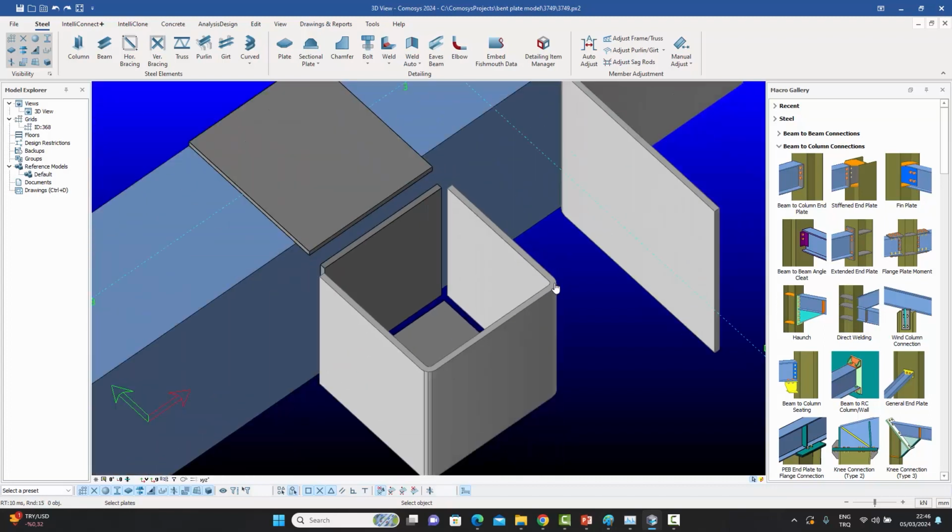it's joined them together. I can then continue to join this whole new bent plate and this last piece over there, this one and this one. And now because it sees more than one possibility to connect, one common edge is over here and one over here, it asks me to choose which one I want. So I choose this one. And when I do that, that one is connected.